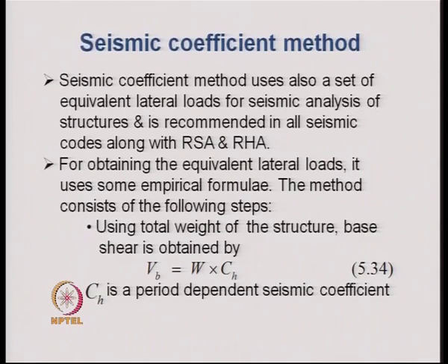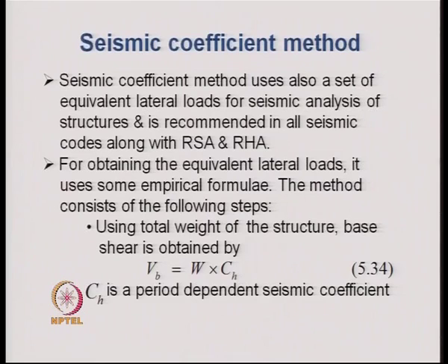In fact, the seismic coefficient method of analysis is more popular compared to the response spectrum method of analysis, because it is purely a static analysis. We do not have to even obtain the time period or the frequency of the structure and the mode shapes of the structure in the case of the seismic coefficient method.